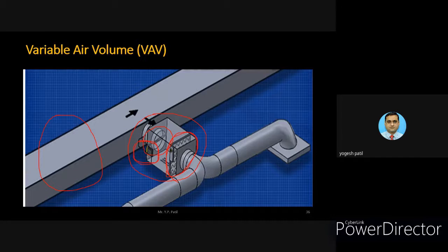This particular subsystem is individually developed for each room, based on how much comfort is required for that room. Based on that, we can individually control the room temperature depending on the comfort required. So there is a controller, there is a damper, there are coils again. This is the sub part that is called variable air volume.